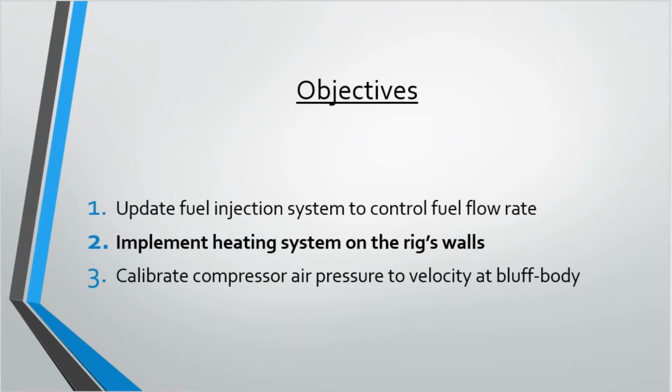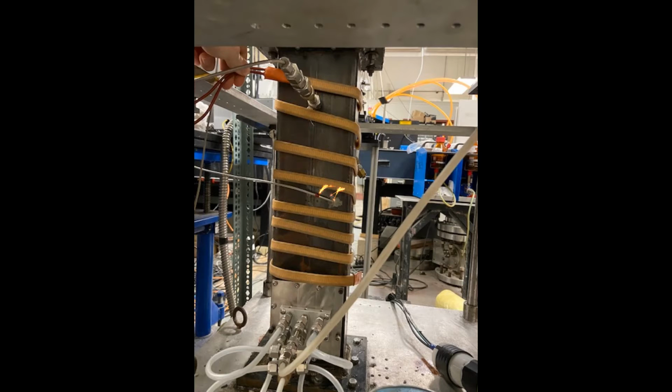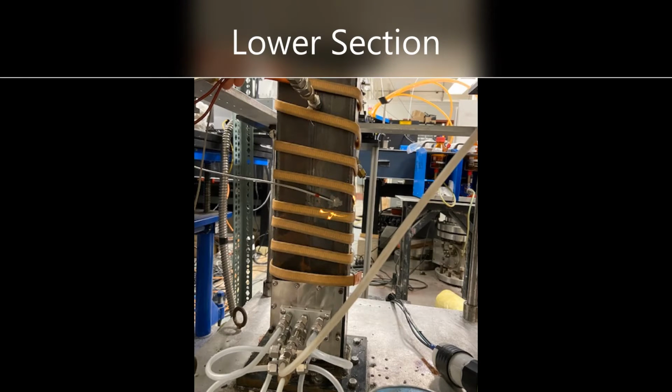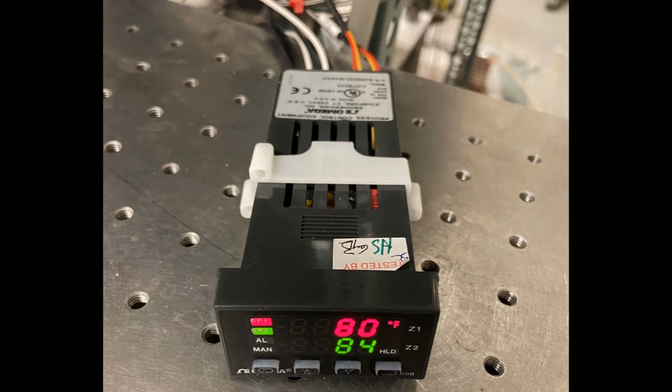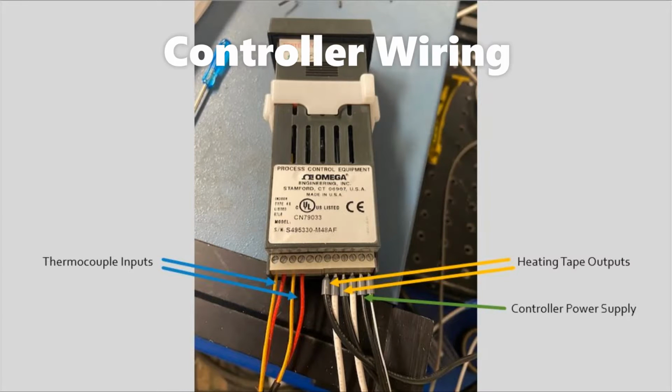There was also a need to implement a heating system on the walls of the rig to prevent fuel condensation. This addition is meant to ensure the fuel droplets vaporize in the airstream and react at the bluff body. This heating system consists of 3 components. There is a K-type thermocouple on the upper and lower section of the rig to monitor the wall temperature. These temperature readings are sent to an Omega temperature controller, which compares these readings to a temperature set point. Based on this comparison, the temperature controller signals the silicone heating tapes at the upper and lower sections to increase or decrease their heat release.